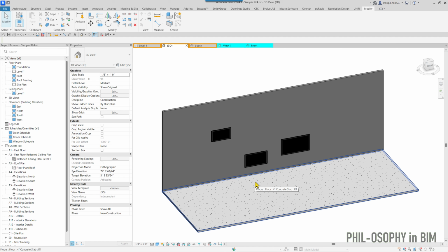You can use this on a lot of applications. I use it a lot of times for a TV or for a mirror, like a wall-mounted mirror. Again, you're going to need that because when your mirror is actually mounted at 4 feet or taller above the finished floor, your mirror is not going to show up in plan view. So in which case, you kind of want to see the mirror in plan, for your design.